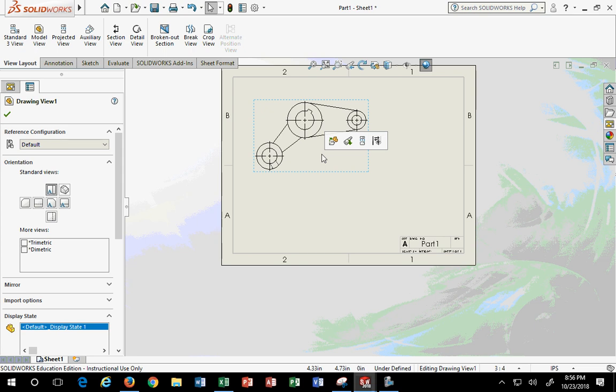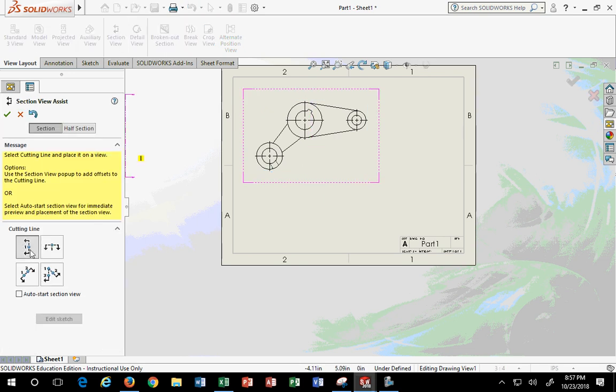In this case, I picked the top view because the basic geometry, the shape, the footprint of the object is much more visible in this view than in other views. That's why I selected this view. Off of this view, when I go back to section, you're going to see that there are different types of sections. Cut line, horizontal, this is vertical. Then there's something called auxiliary, and then aligned. This is the one you're doing today, aligned.